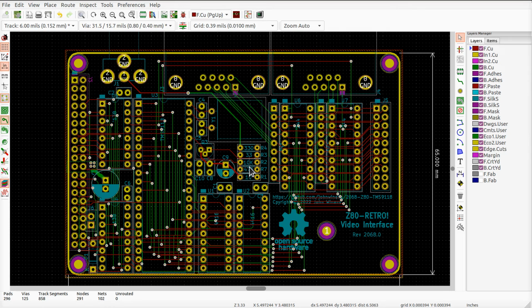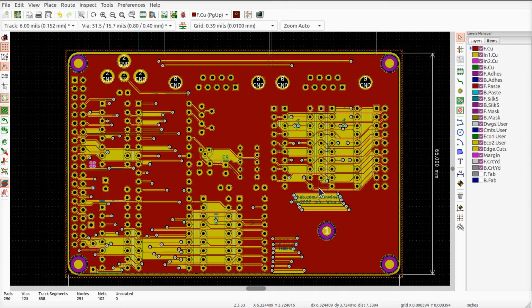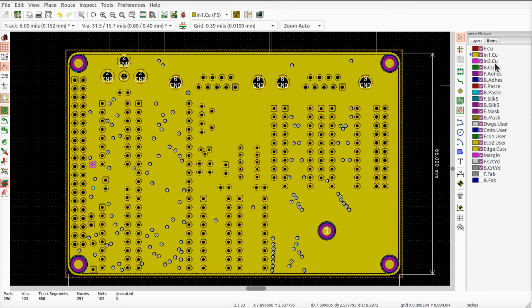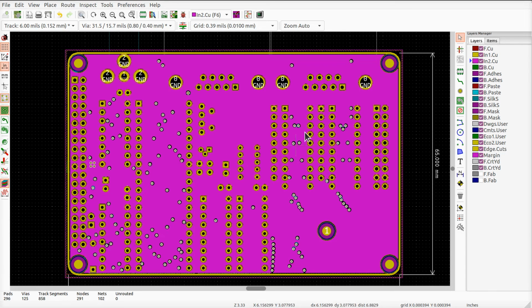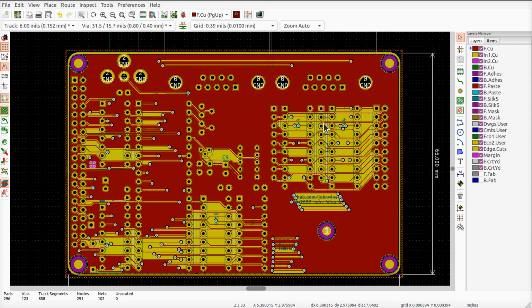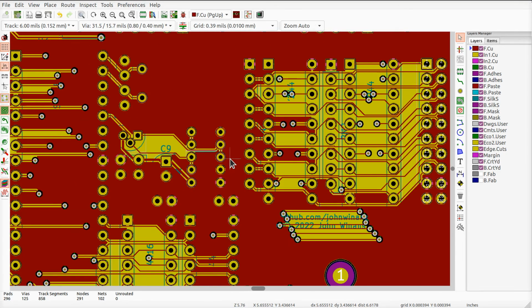And by the way, I went with 4 layers on here. It may not need 4 layers, but with 4 layers, you've got a giant ground plane in here. If I turn on all the layers, inside here, there's not going to be a lot of loop currents or anything. And yes, I know the inner layers are going to be, like, 5 volts and ground. So as we go between the top and the bottom, I don't have stitching vias. Maybe I should put some. I don't know. Maybe I'll tweak some into the design before I order the boards. It'll work without them. It may be less noisy and more robust with them. I'm just saying. Maybe.